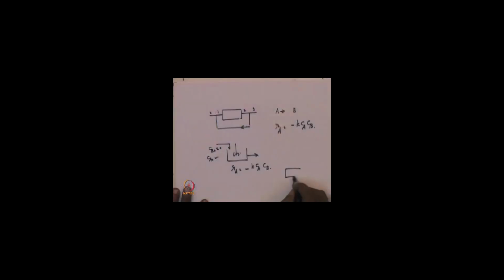But if the same thing is to be done in a PFR without recycle, if you have to do the same autocatalytic reaction in a PFR, because there is no mixing here, and therefore, the feed does not contain product, you will find the reaction will not take off. So, PFR is not effective for autocatalytic reaction. Okay.